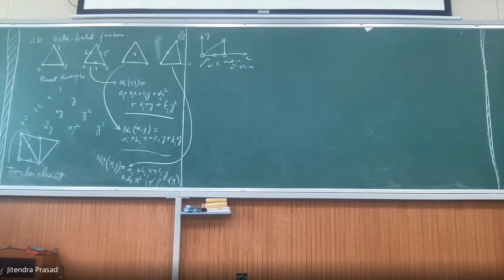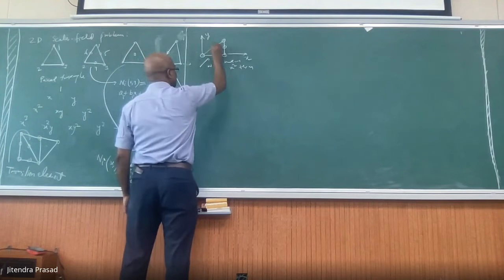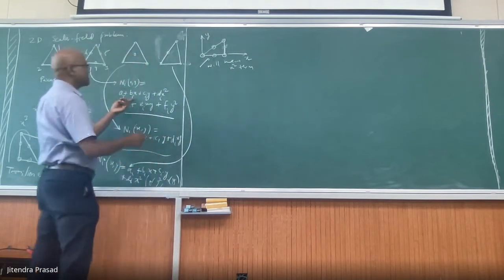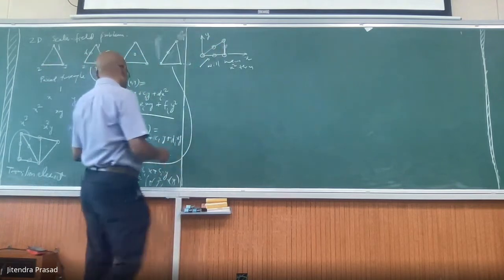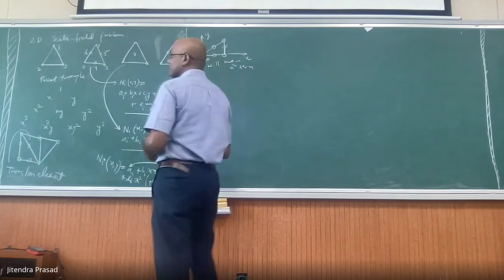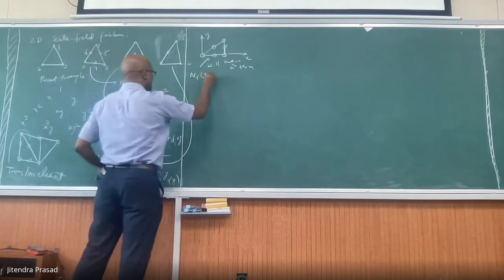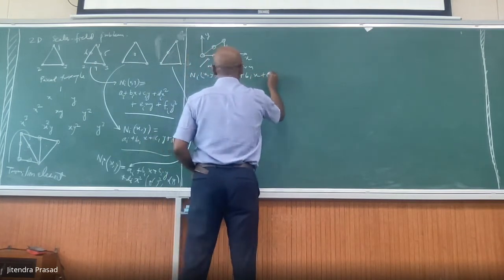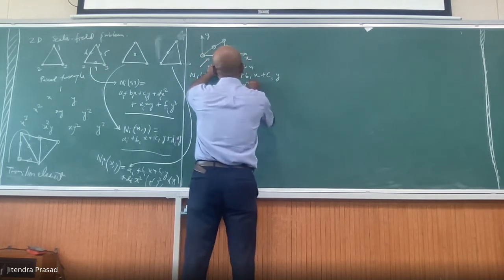But if the x is equal to y line, that's the hypotenuse. Then you will have one xy term there, right? Then you will have five of them, no? So you will need 5 terms. So one of them will not be there. So in that case, you will have Ni(x,y) equal to ai plus bix plus ciy plus di. For sure it will have the x square, right?